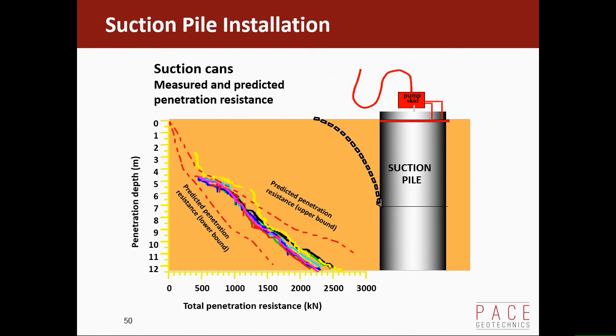Another thing about suction piles is the suction is used to penetrate the suction pile. The suction is not maintained during the life of the pile. Okay? You switch it off. They leave the top of the pile closed, but if the pile is being pulled upwards all its life, say for a riser base, which the riser is obviously designed to be buoyant and tied down to the seabed, you might use the weight of the pile, and you might allow for some adhesion on the side of the walls of the pile, but you don't allow for suction in the pile.